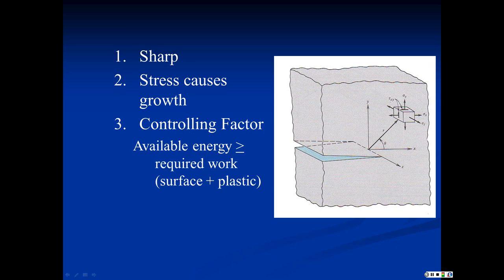and it's the energy stored out here in the stressed material. You may think of the resilience of the material. When you've loaded it up, you've stored a lot of energy elastically. What's this energy that is stored in the material that is going to do the work of causing the crack to grow? And that work has two components.